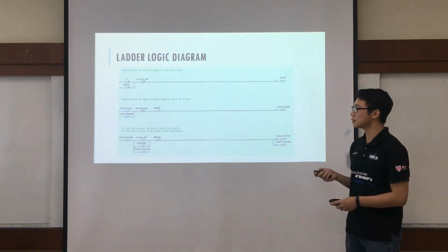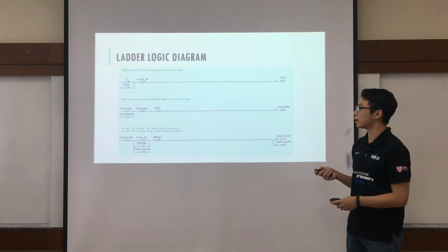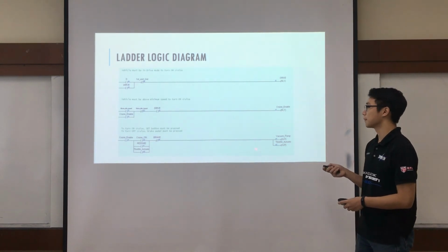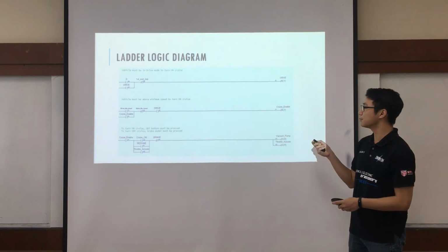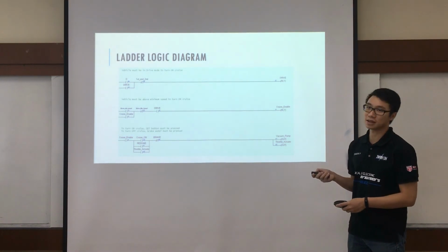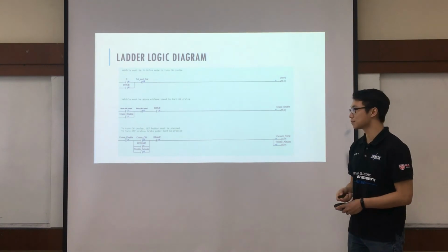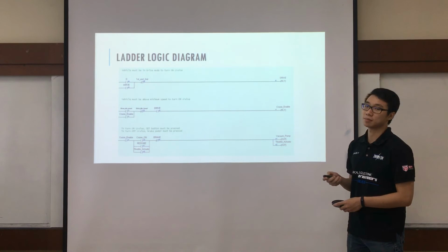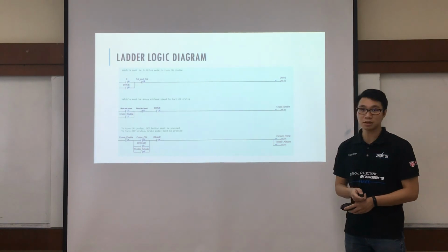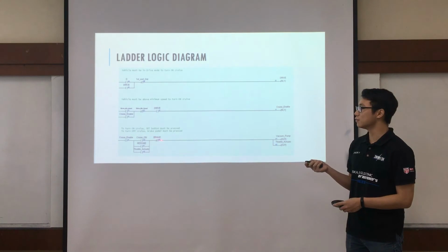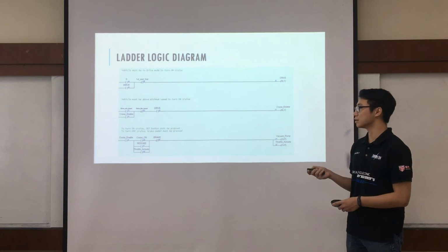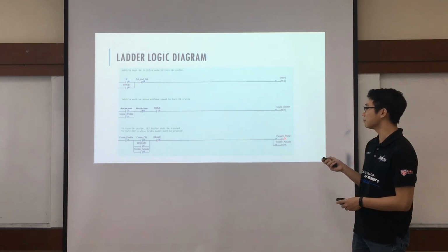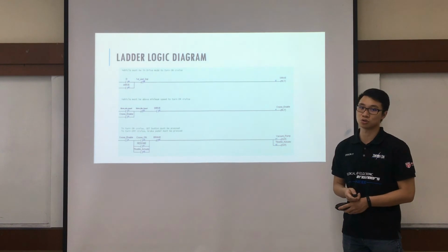Thirdly, we look at the third part. We'll see that cruise enable and cruise on need to be turned on for cruise to take place. So we can see cruise enable is the relay that is right here. Cruise on is actually a button that needs to be pressed if we want to turn on cruise. Resume is another button that we can press if cruise has been disabled temporarily but wants to be resumed. And finally, we can see that brake is a normally closed contact that, if energized, will break the circuit and will de-energize the vacuum pump and throttle actuator, which is used for cruise control.